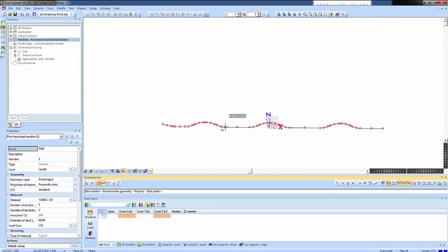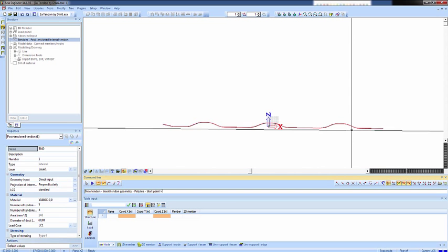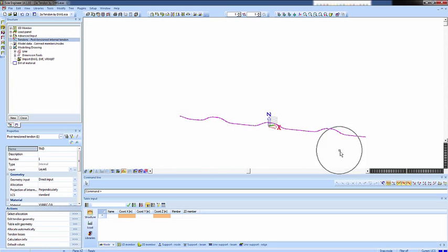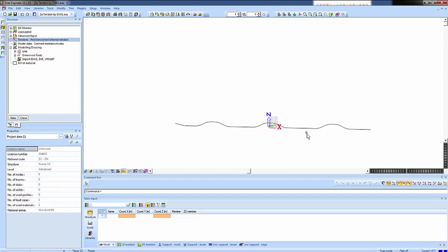And I'm going to place this tendon into the project, and to make it easier, I'm just going to follow my DWG. So I choose select line, and I can just pick this line. And now this is my tendon in the material. Of course, this does not work. I think this is logical. This is very logical. It will not.